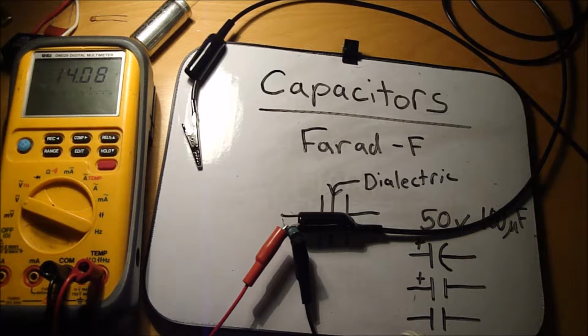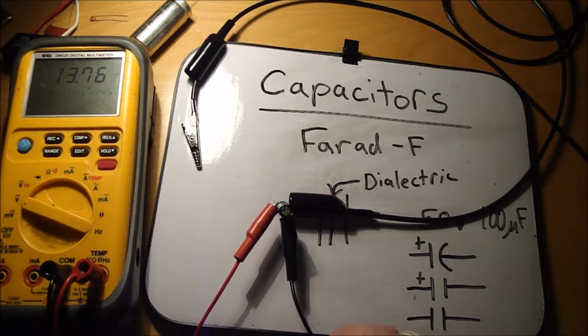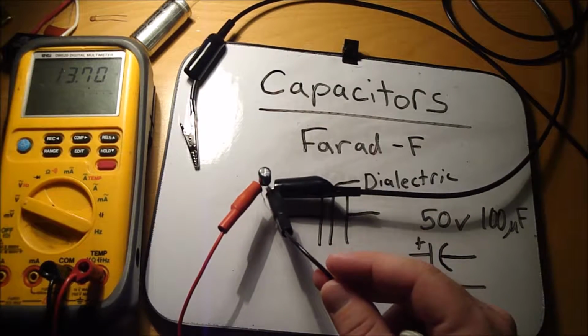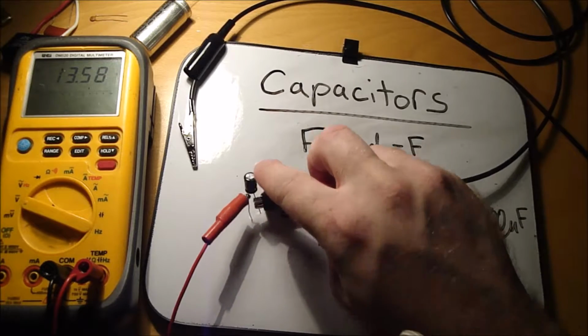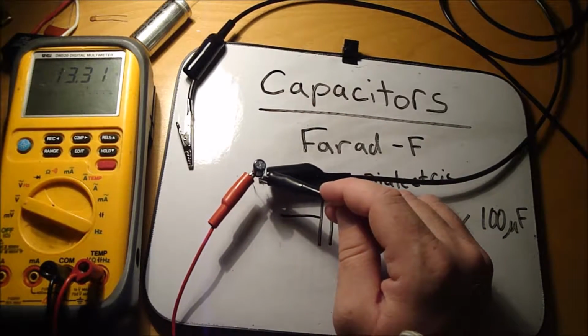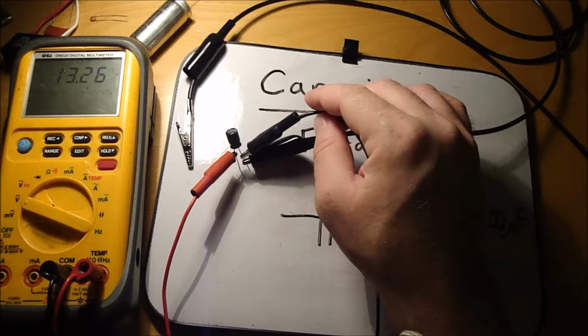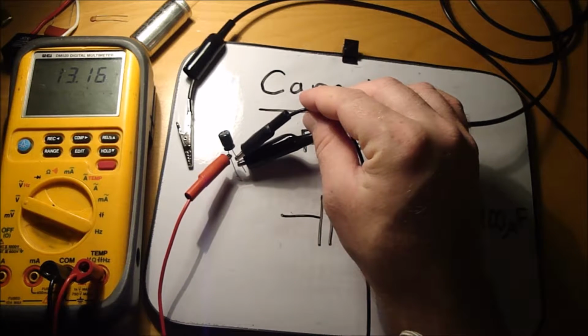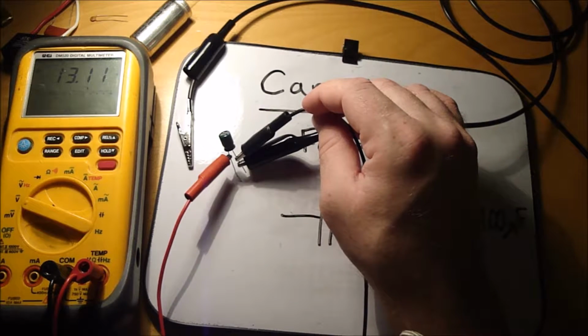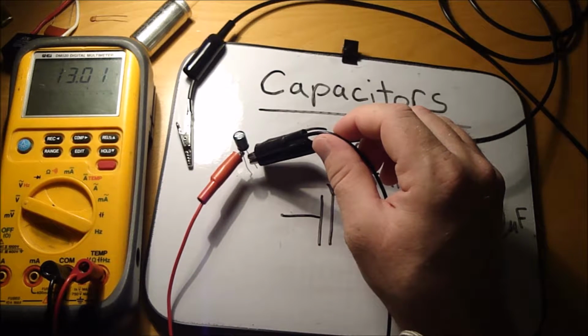Capacitors do have a very small internal resistance, and the resistance gets lower over age. They just lose their ability to hold a charge over time, especially the electrolytics. The electrolytics I see go bad more than any capacitor. They will start to bulge on the top. They'll start to leak out their dielectric. It's basically an oil. It's a film of paper in there soaked in a dielectric oil. So it's holding a charge, it's just starting to slowly drop.